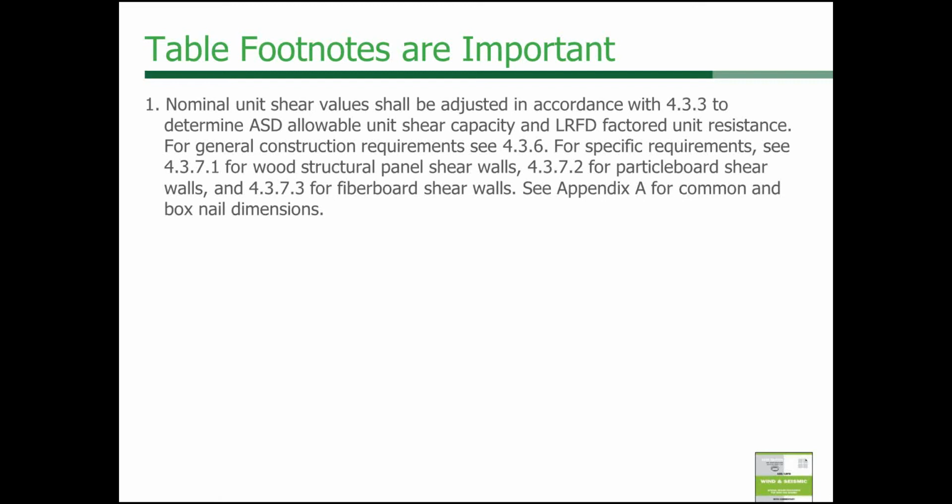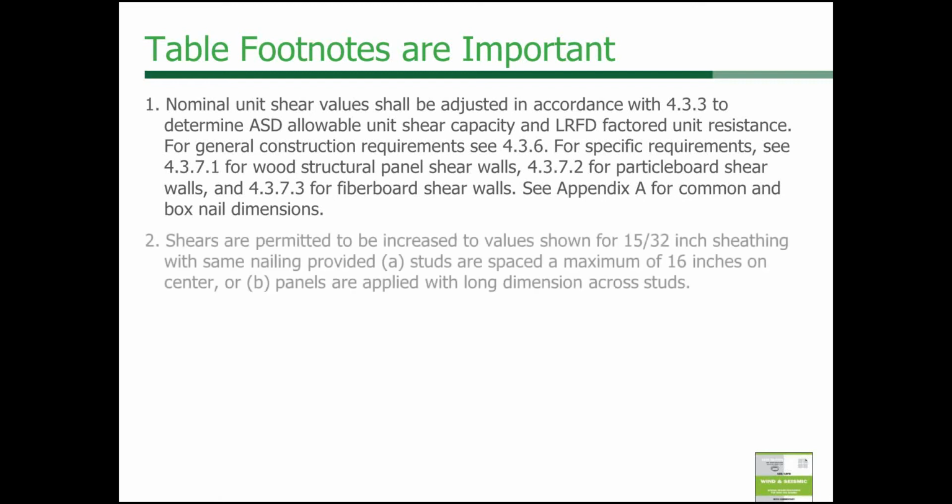And the first, and this is very important, is that this table is based on nominal unit shear values. And given that this is a dual format document, we need to reduce that value based on whether or not we're doing ASD or LRFD. And this footnote tells you what section to go to if you're doing ASD or what section to go to if you're doing LRFD.